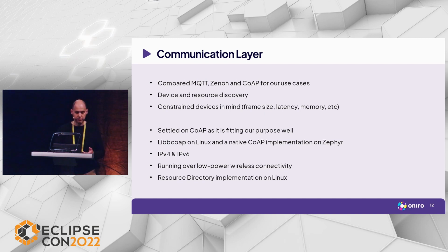We wanted to have device as well as resource discovery, most likely built into the protocol, so we don't have to develop anything on top of that. And as I mentioned before, we want to have constrained devices in mind. Constrained is a very generic term, I know that, so we wanted to make sure that we make good use of small frame sizes. So if you run on low power, low rate wireless communication, we want to make sure that it is working.